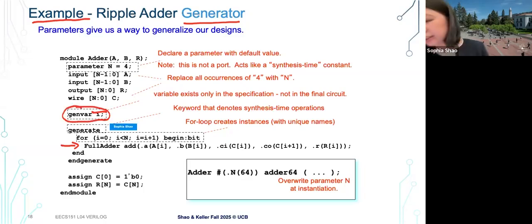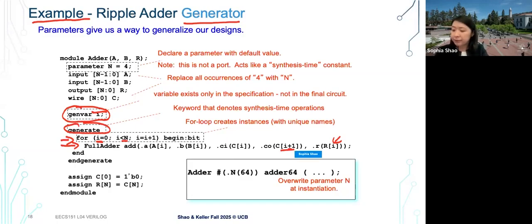Instead of explicit full adders, you can use this generate statement, and with it you can introduce a loop. You can use a loop to describe multiple copies of the instance here. So in this case, you have a more parameterized design. You can use this genvar i, an index here, and use a different index to describe the loop, like the different bits being used.